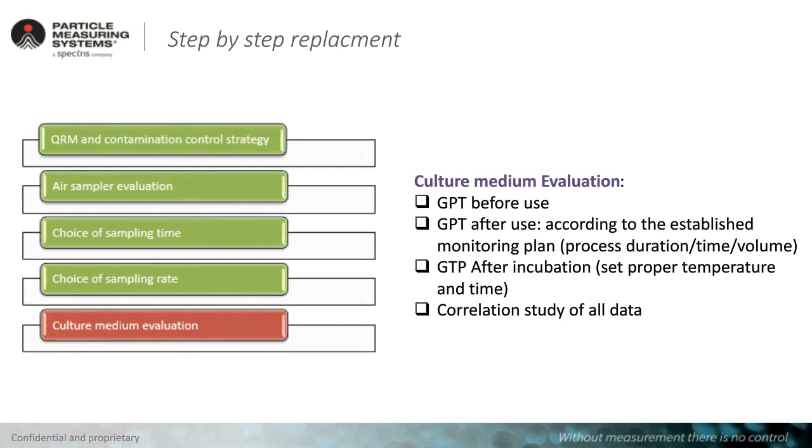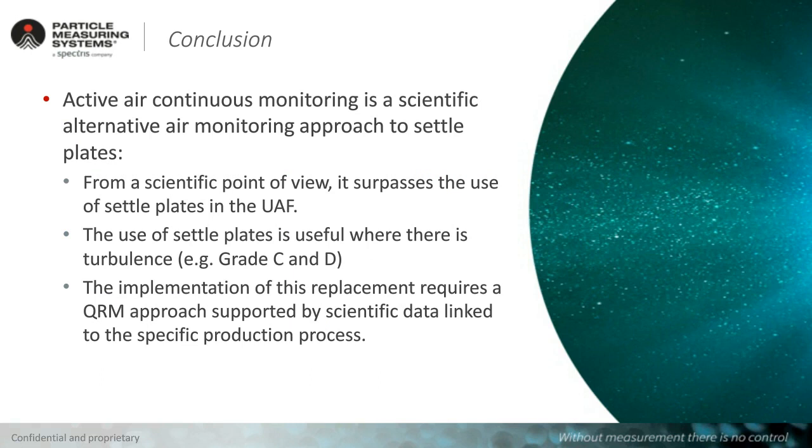As a conclusion, from a scientific and literature perspective, we need to understand that settle plates in unidirectional airflows and in critical environments are not really a favorable methodology. We know that the use of settle plates is very useful where there are turbulences, less airflow, etc. So still in grade C and D, we have very valuable data telling us what's happening in these gowning areas, for example.